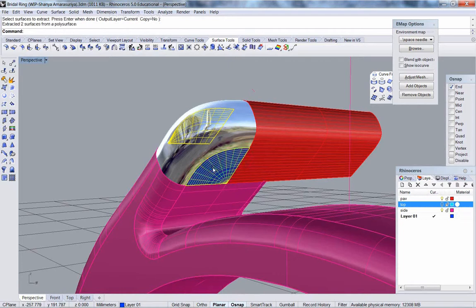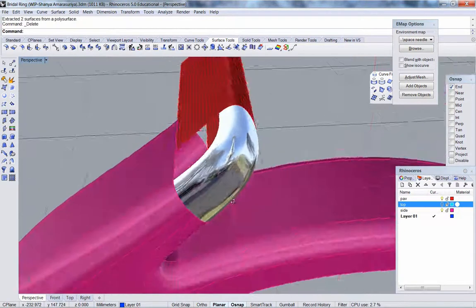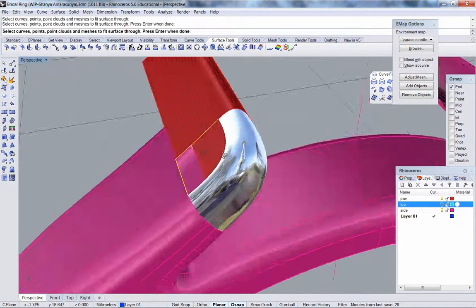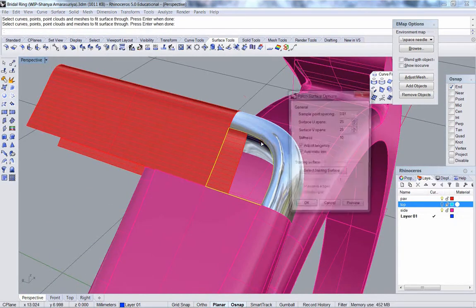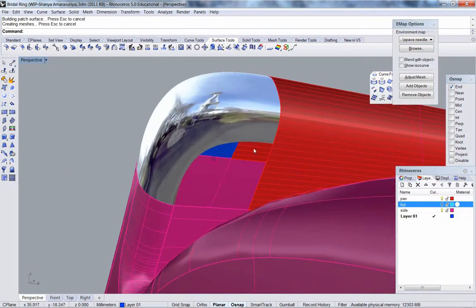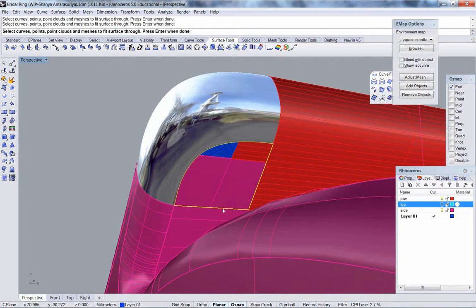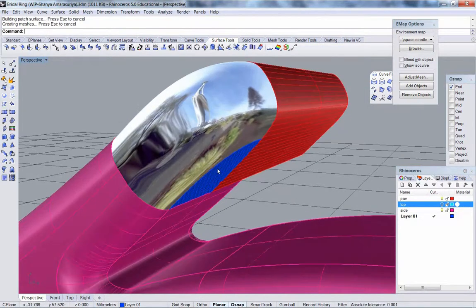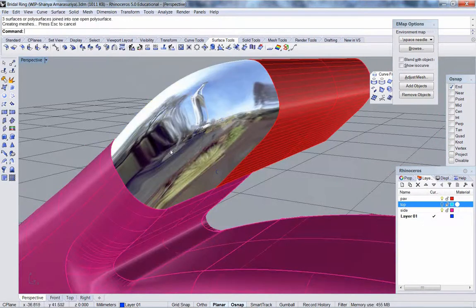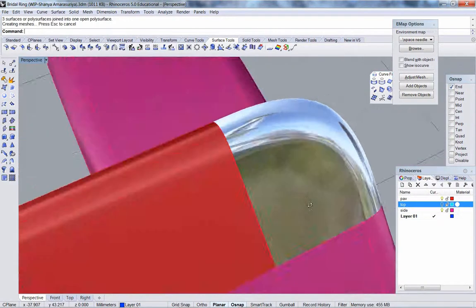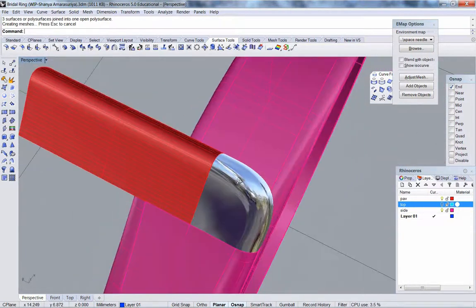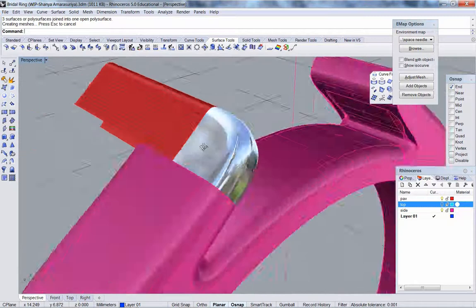And there are times when the best surface for getting something smooth is a patch. And which times those are by experience, unfortunately. But I think this is a very good opportunity to use a patch. Because there's not a lot going on. It's pretty flat and smooth to begin with. Would it have a bump? Oh no. Or, well, ever so slightly because it's coming into a flat surface. That's a lot smoother than a fillet's ever going to go.